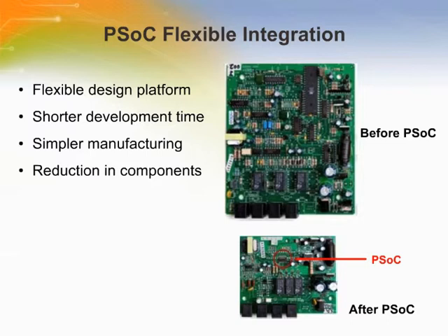All of this flexibility and configurability manifests itself as a highly flexible design platform, allowing for more rapid design changes and easy migration to new projects. This reduces development time and simplifies manufacturing. The integration capabilities of PSoC reduce the component count as shown in the figure here. The figure on the top is before PSoC and has considerably more parts, ICs and passives, than the board on the bottom.